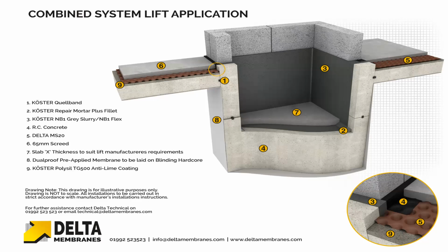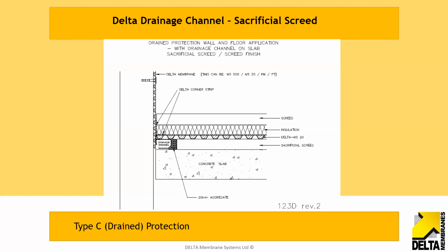We can't put sumps and pumps in lift pits. So don't really specify lift pits that are built from block work, because that's not very good, because that's very permeable and it's not great for preapplied fully bonded membranes. Try and specify lift pits in reinforced concrete would be my honest advice, and it'll save everyone a lot of headaches.